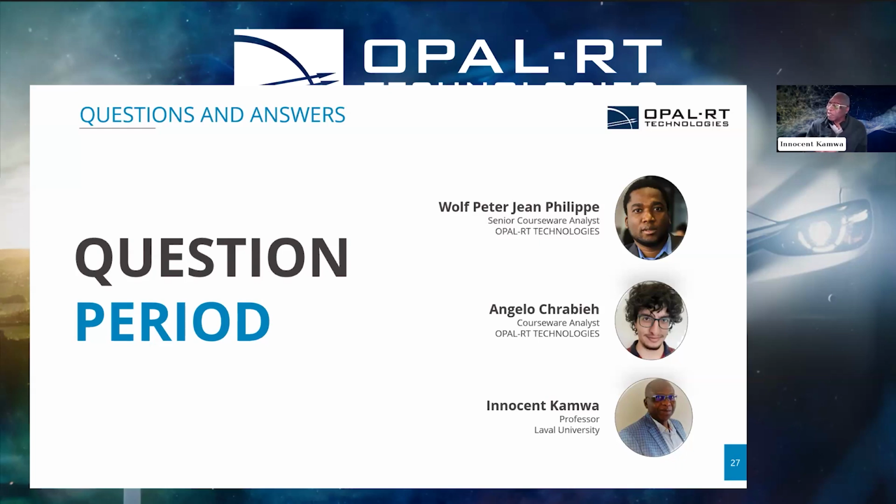And also because HYPERSIM is a parallel computer, it can simulate a very large system very quickly. It is actually very difficult to beat HYPERSIM in offline simulation because it can split the network into multiple cores and speed up the simulation automatically without human intervention. So that's something I wanted to add.